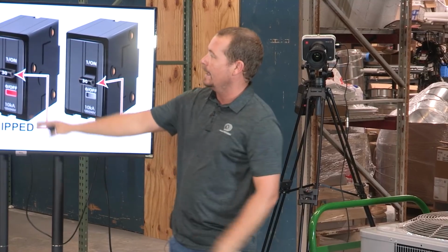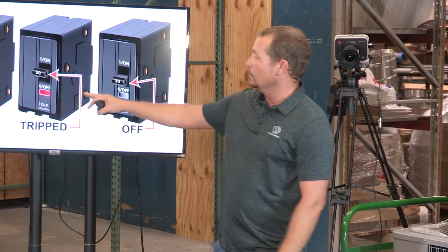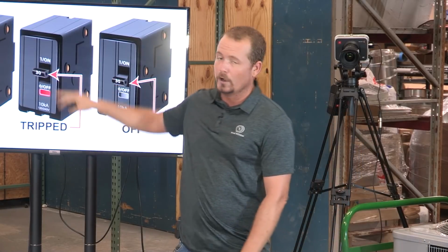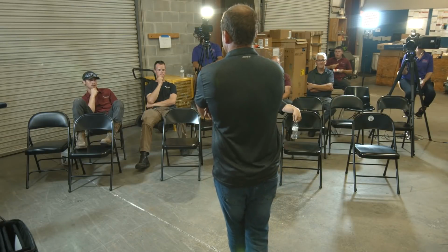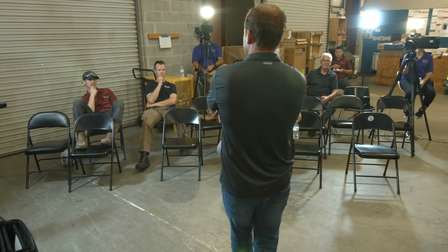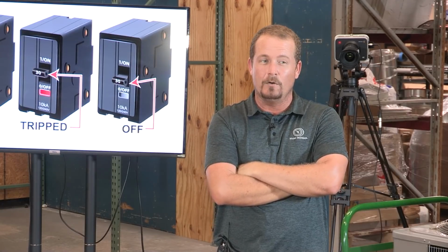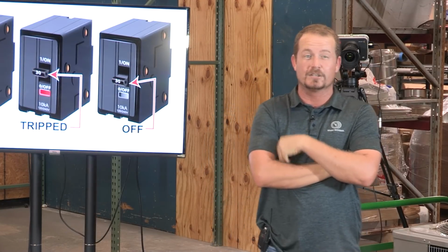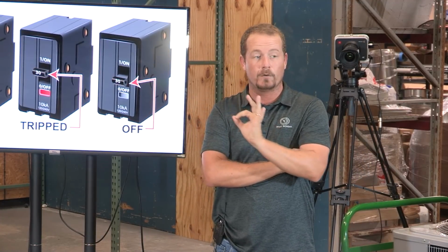If we had a breaker like this one, this is a Square D Q0 2 pole, and we were running a system that was drawing 30 amps, how long would it take to trip? It might never trip. Now, it should eventually, if we're drawing just a little bit over that, 31 amps, it should eventually trip. But is it going to trip right away?